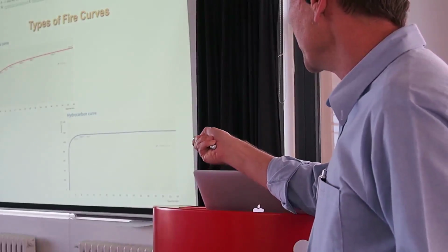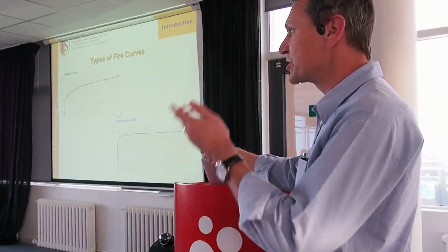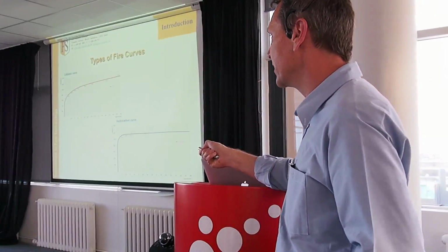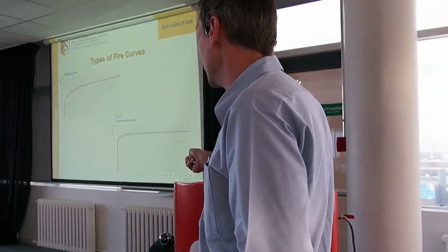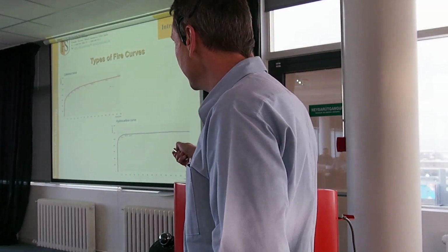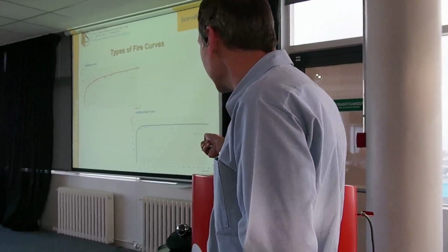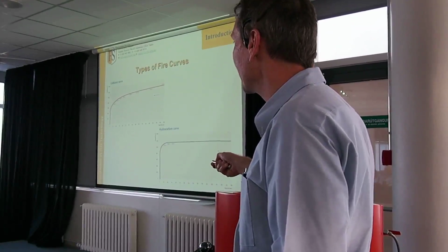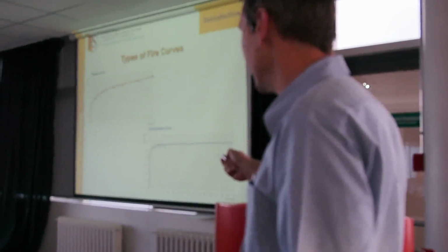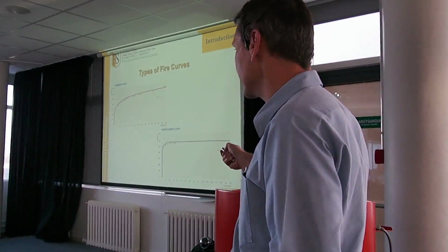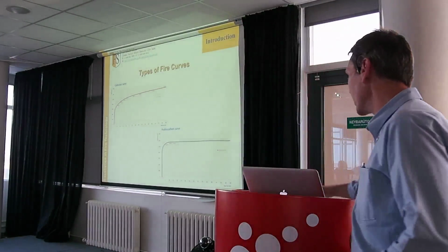curve, which is your typical office buildings, your cinema complexes, your steel plants where there are no hydrocarbons or fuels or oils. And this is your typical hydrocarbon fire curve. The difference is that cellulosic fire curves run at a slow growth rate, compared to a hydrocarbon fire curve, where within about 45 seconds of ignition you're at 1100 degrees Celsius. We do protect both types.